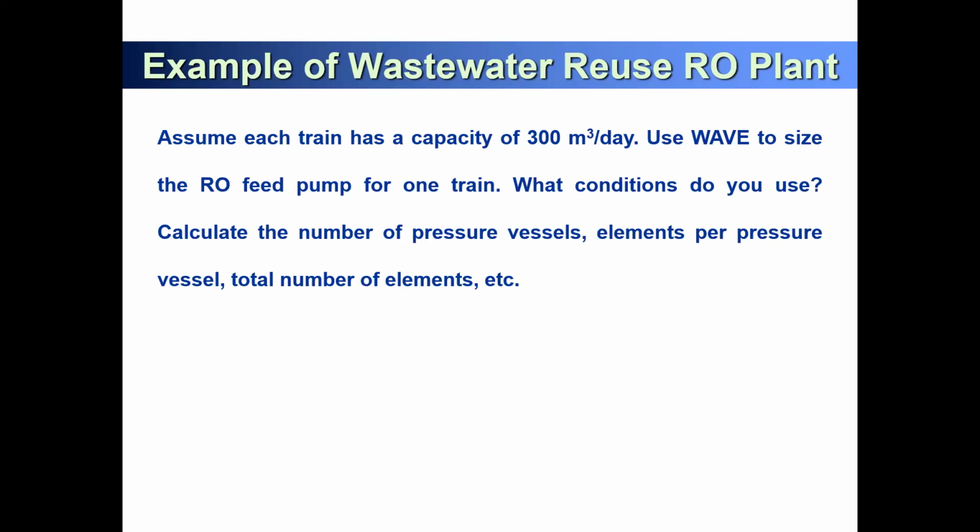When you think about seawater desalination, the concentration is 3.5% and the osmotic pressure is 28 bar. So we apply a pressure of 60 bar, and we can design for 50% recovery. But if you go a little bit more than 60 bar, what happens to the membrane?